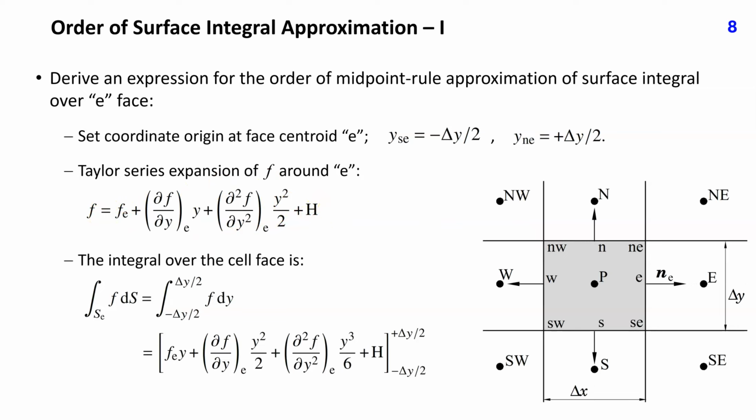We can now integrate the function f analytically from SE to NE. Note that the derivatives of f with respect to y at location E are unknown, but at the fixed location they are not function of the coordinate y and can be treated as constant in the integration process. This makes the integration straightforward. The final expression now needs to be evaluated for the integration limits.